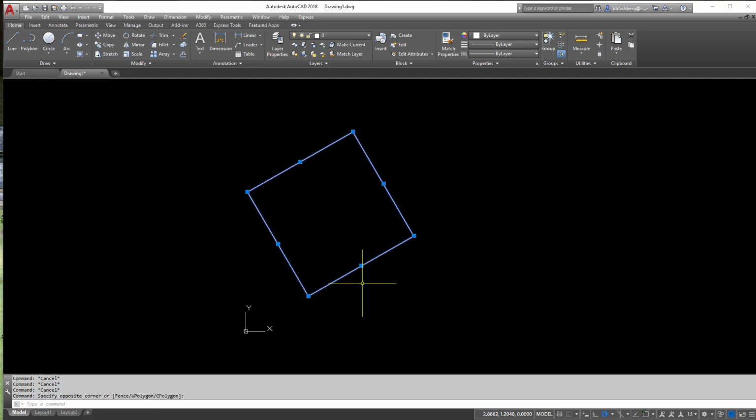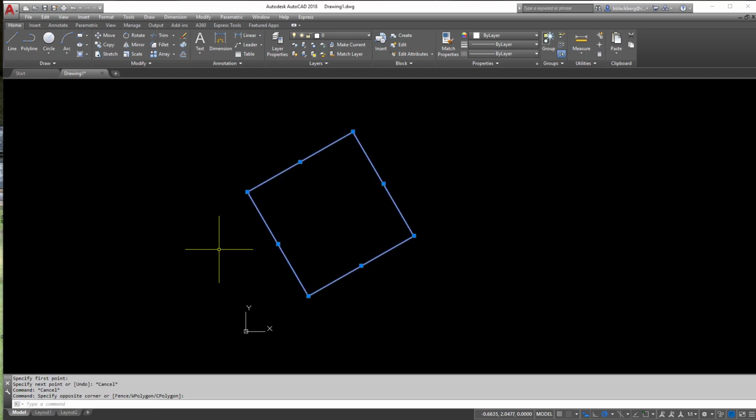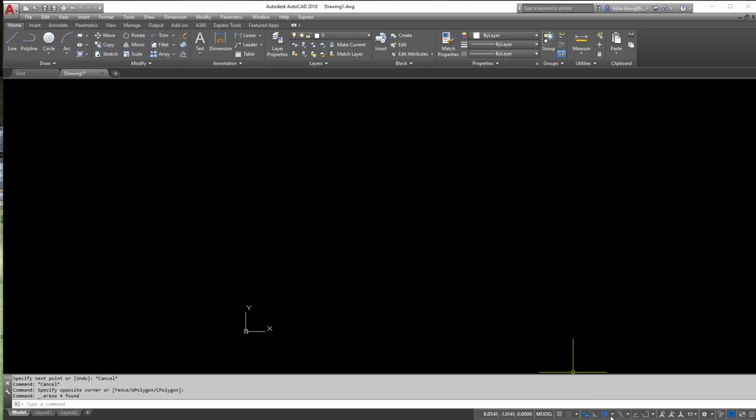Now, when drawing lines, you'll notice there's probably a million different ways people are going to do it. The best way, personally, if you're going to learn right from scratch, is probably to get used to using this dynamic input mode and learn from there, as this is probably the easiest way to draft things. Now, there's a few other ways. If I just had to make things 90, you might notice that polar tracking has 90. Well, there's another command right next to polar tracking called ortho mode. And if I turn ortho mode on, I can really draw a quick box, no problem.